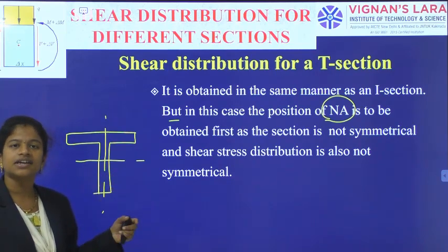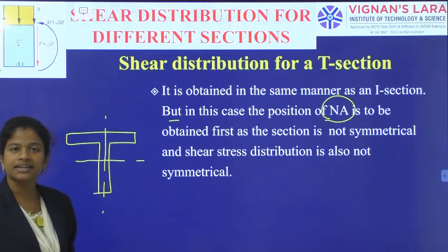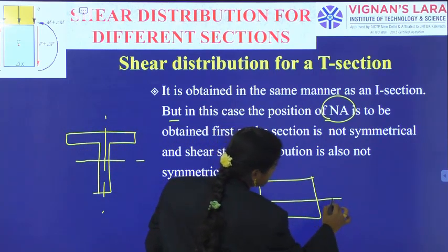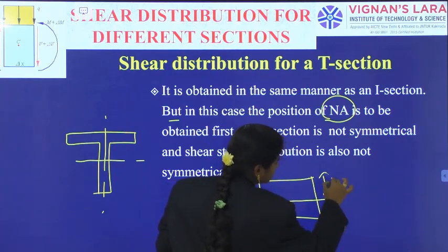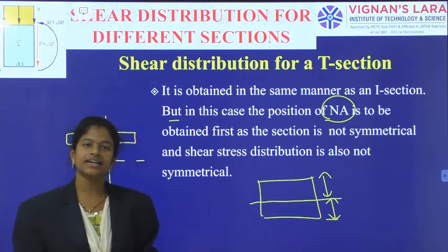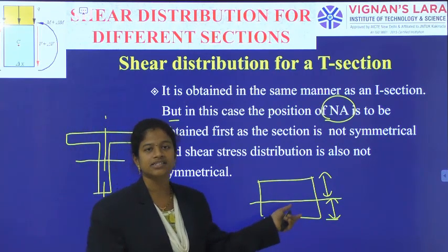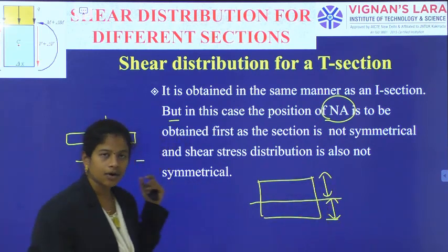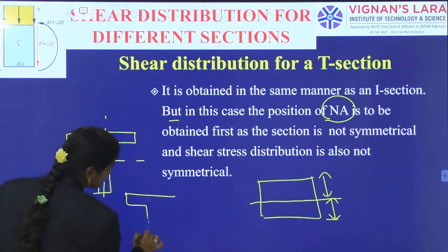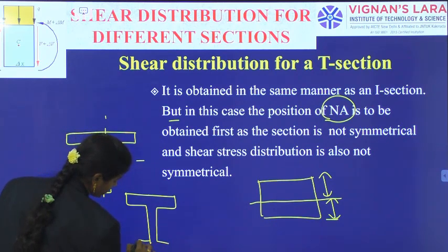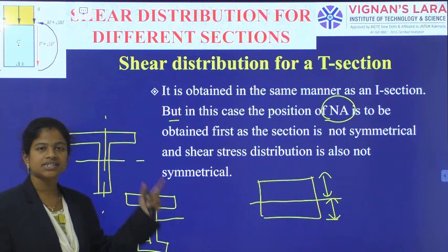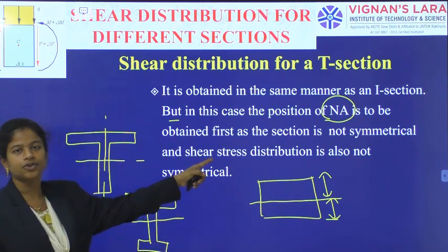Generally, for the symmetrical sections, the neutral axis will be at the geometrical center line, simply the horizontal line which we draw at half the depth, right? For any symmetrical section, overall depth by half, that is our neutral axis line, geometrical center line and centroidal axis line for the rectangle, circular, square and symmetrical I sections. Now, being unsymmetrical, for such T's or some unsymmetrical I's, we should locate the neutral axis. So, for such unsymmetrical sections, our first target is generating the neutral axis location.